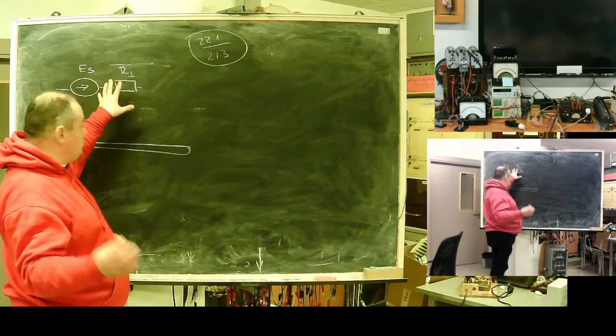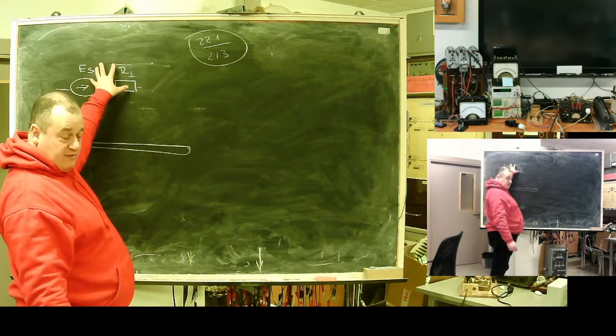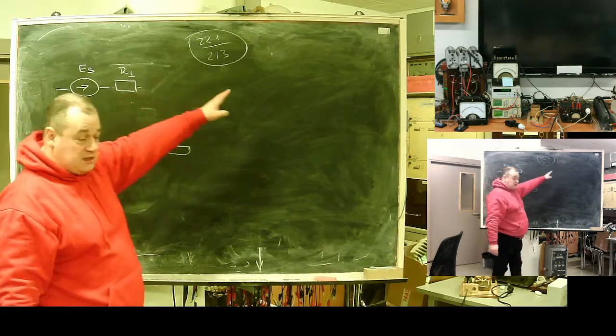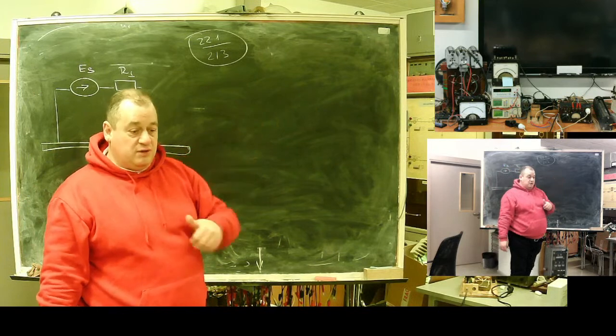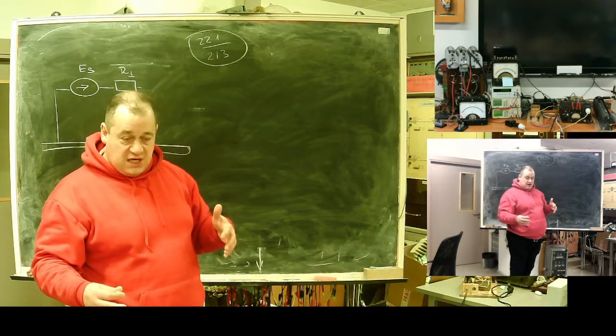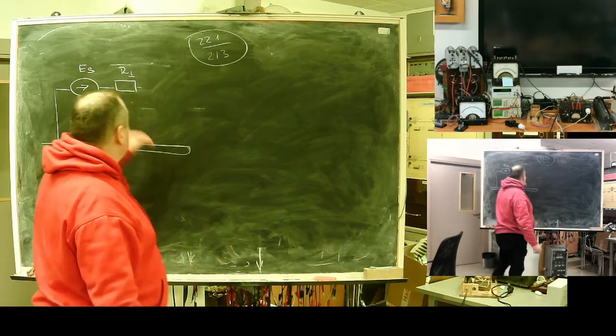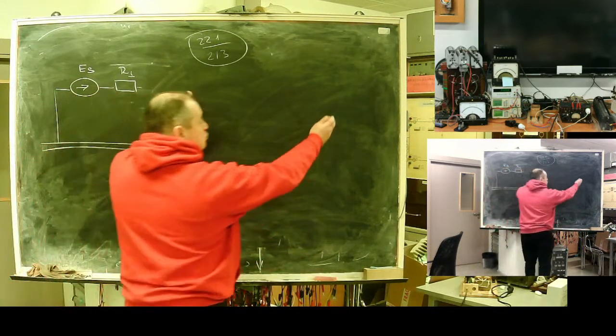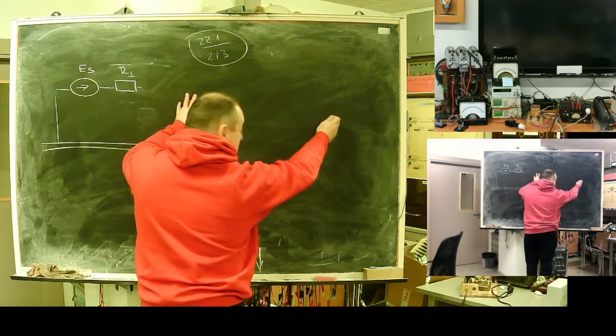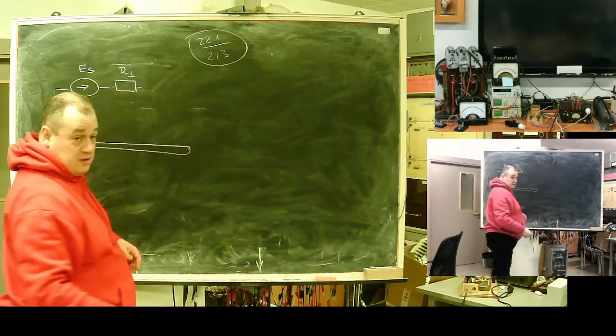In the real world, this will be at 11 kilovolts and the part after the transformer at 0.4. So if you decide to perform this reduction to 11 kV, you don't tackle this part, the factor will be 1, but you will need to raise the part after the transformer to 11.